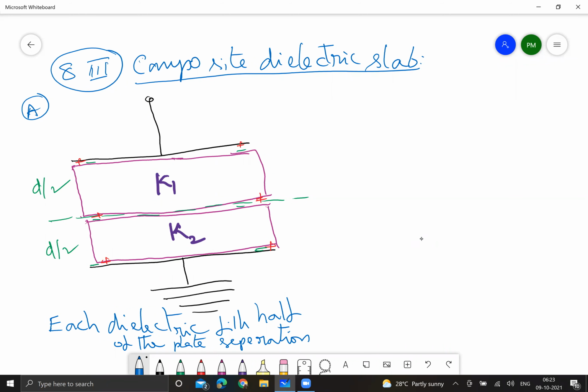So now we can write the capacitance; we can assume it is equivalent to two capacitors, because we already said the dielectric slab acts like a conducting plate with equal and opposite charges on its two faces, establishing a field across it. Therefore, the first plate of the capacitor and the first face of the dielectric will comprise one capacitor.